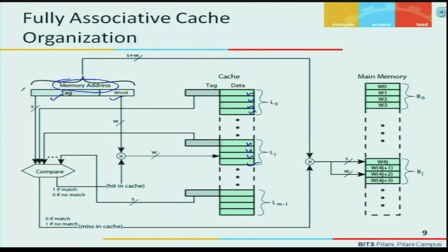Now, for any given address, how do we find whether it is there in the cache memory or not? For each block of data the tag is unique. If you write the sequence of 16 bits from all zeros to the maximum, 2 power 16 minus 1, you will see that after every 4 addresses the leftmost 14 bits combination changes. That means the tag bits, as in the example I discussed in the previous slide, are different for each block.